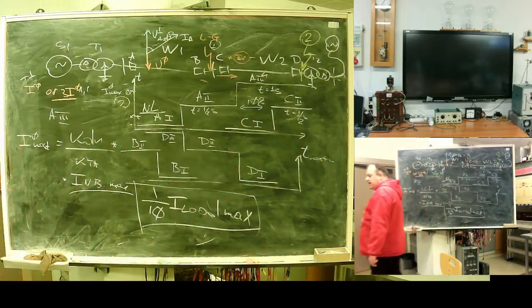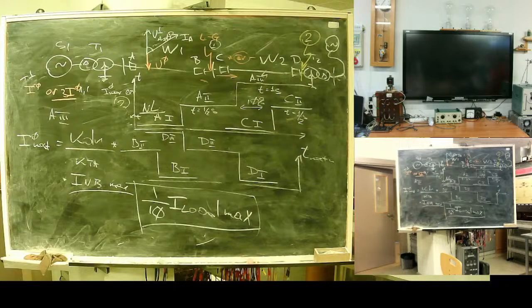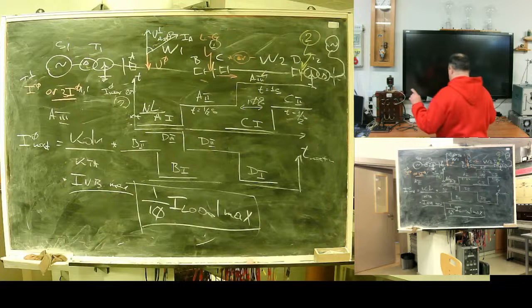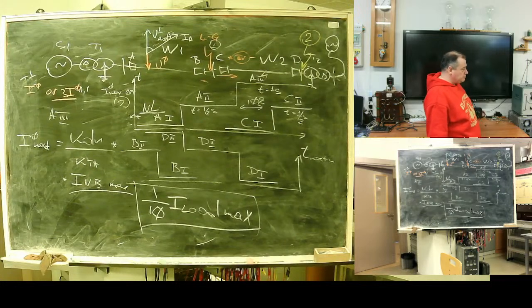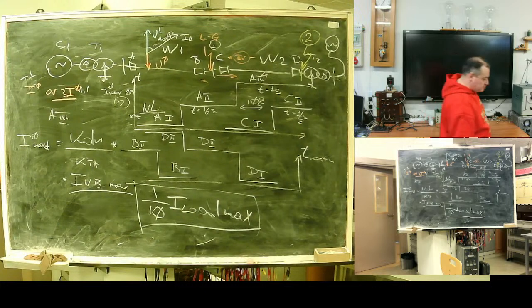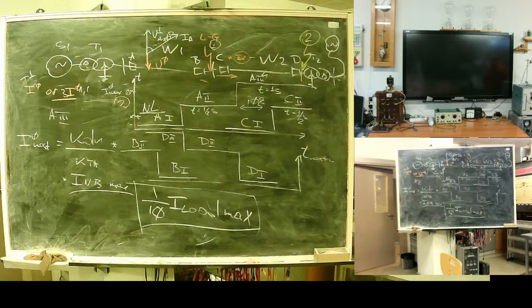Really. It's more sensitive than the distance protection. That's why here we have problem. Earth fault with trees, with high internal resistance. Current in case of such fault is so small that distance protection cannot operate safely.